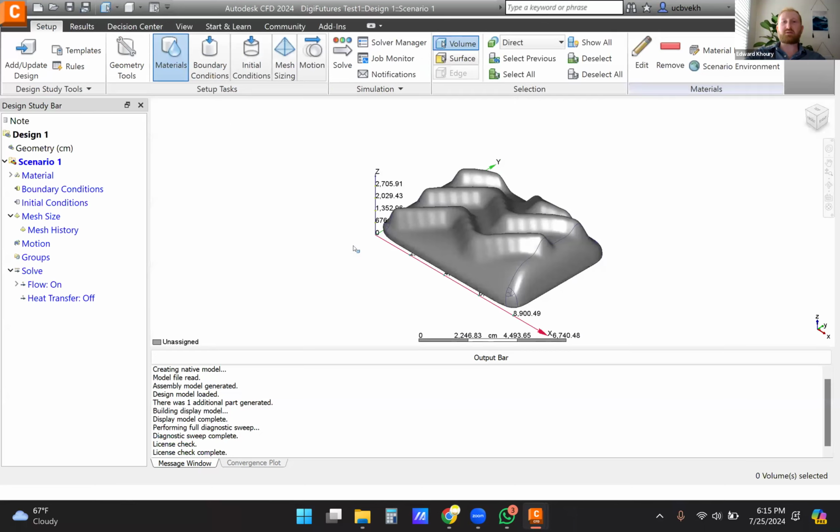So I had modeled this through SubD and Rhino. Typically for CFD, what happens is that the models get really complex and often crash or never load. So I highly recommend if you're going to model something in Houdini, the next step is to have it modeled and do a simplified version of it in Rhino so that you can actually load it and do analysis. So maybe just one portion or one part. And I can show you an example.